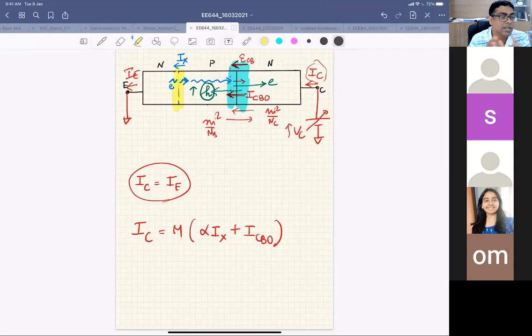And at that point we call it the breakdown. So in this case, this is BVCEO. There is no junction between collector and emitter, but I call it collector-emitter because this is the breakdown voltage: at some collector-emitter voltage, a high current flows across the transistor. That voltage I call BVCEO, because my base is open.